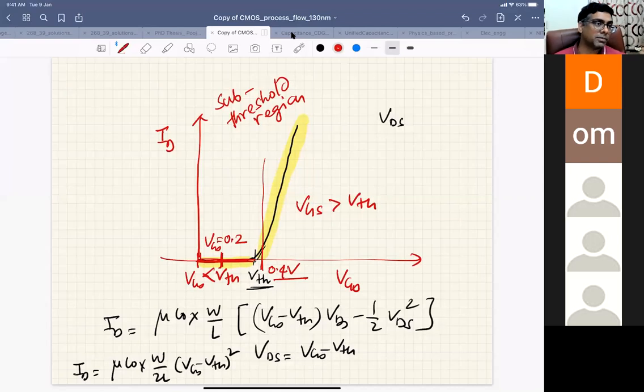That means I do not have a lot of electrons, but I have electrons, right? I will have electrons the moment your VGS is more than zero, or more than flat band voltage, right? And these electrons will also flow because I have a VDS. That means the current is not zero. There is a finite current, and that current we call the sub-threshold current, and that current behaves like a bipolar transistor. We'll come to that point in the next class.